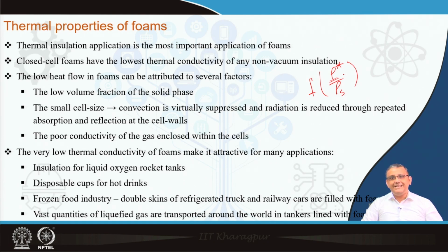Also, the foam cell size plays a very important role, because, as we will see afterward in today's lecture, the cells typically have up to a maximum of millimeter and mostly sub-millimeter dimensions, typically at the micron level, and these dimensions do not allow sufficient fluid convection, which also reduces the conductivity of the overall foam.